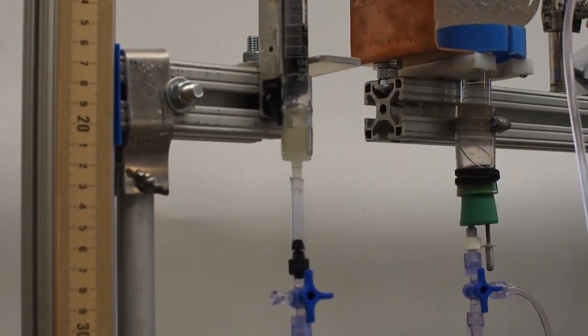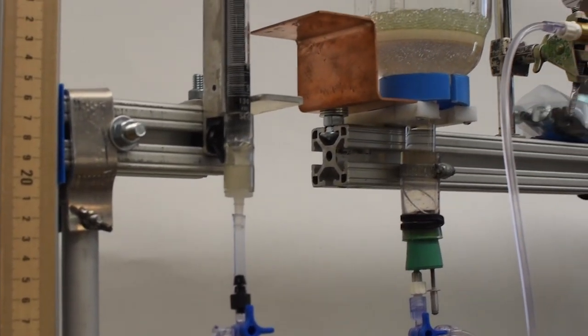After completing the drying process, the same processes but with reverse burette level control are used to conduct the wetting water retention measurements until the burette position comes back to the initial level. You can specify the number of repetitions of these drying and wetting cycles in the program. The system terminates at the lowest burette position of the final drying cycle. This completes the automated measurements.